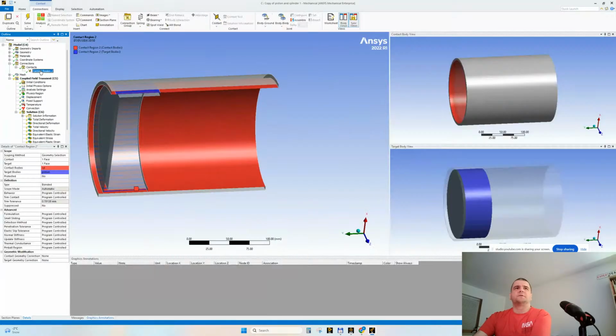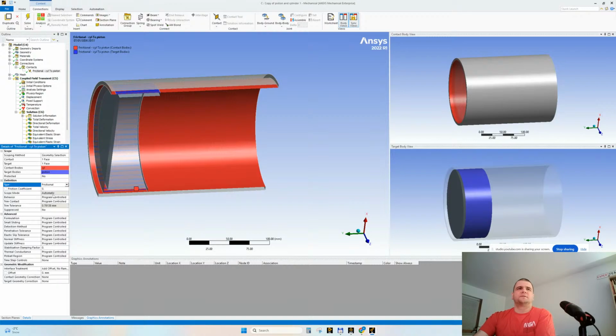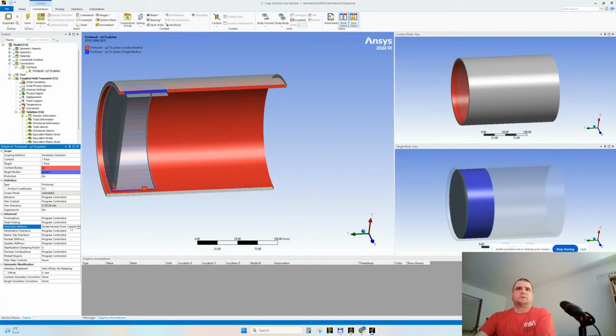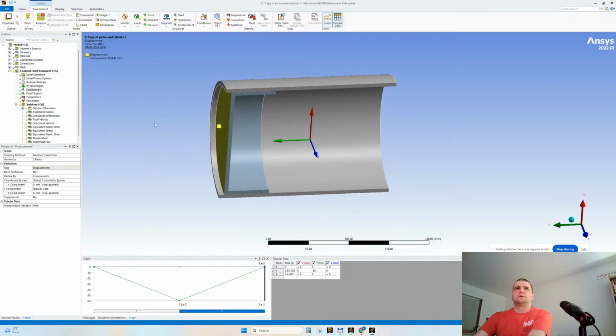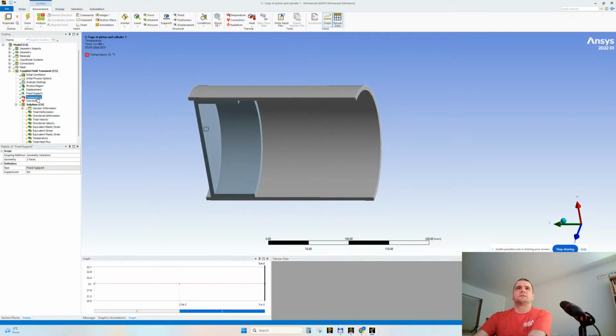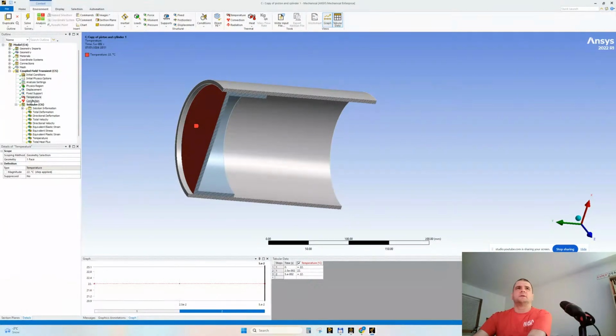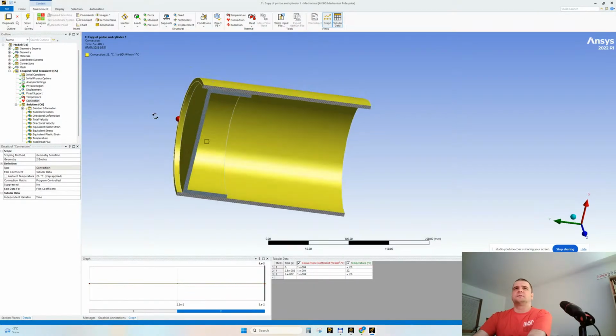Should I increase the friction coefficient or not? It changed the default contact, yes. So let's go again to frictional 0.5, and here we had, for detection method, nodal normal from contact. Was the contact like this? Maybe it was the other way around. Let's see. All right, physics region correct, displacement correct, fixed support yes, temperature yes. Convection, yes.